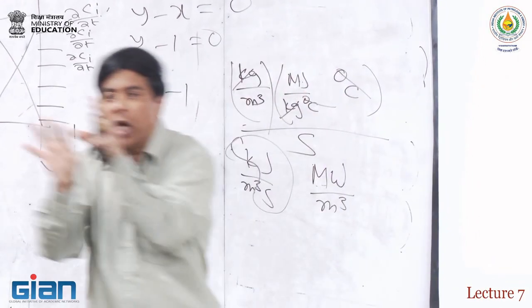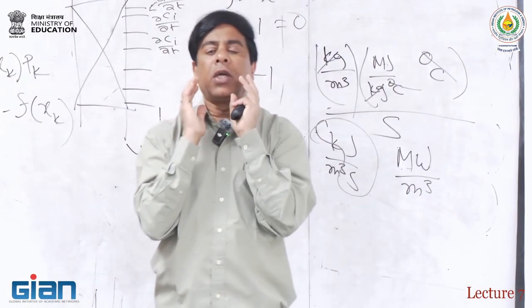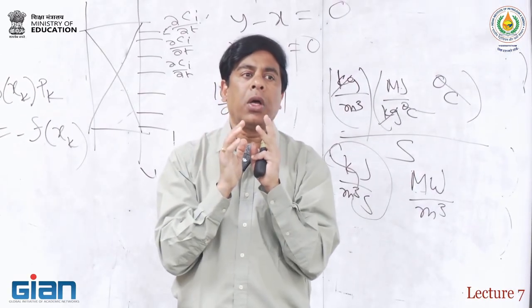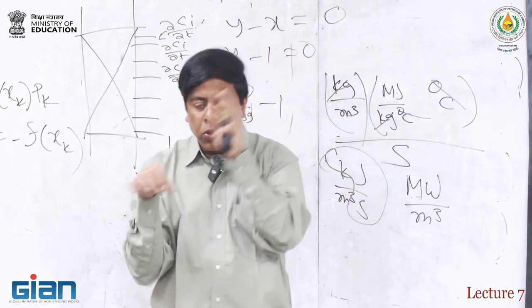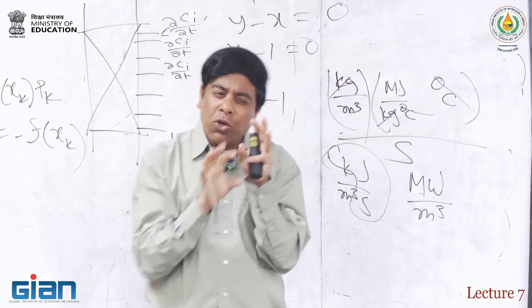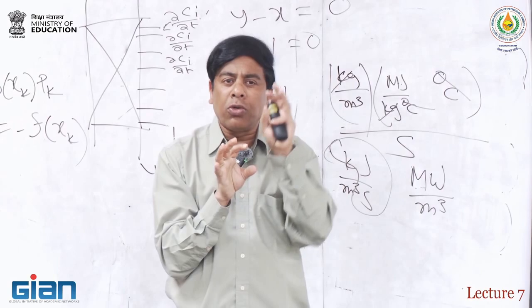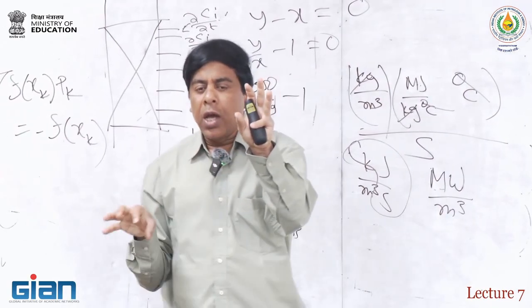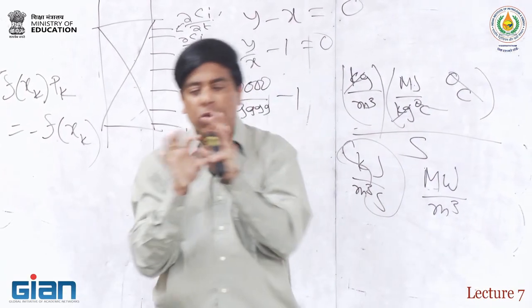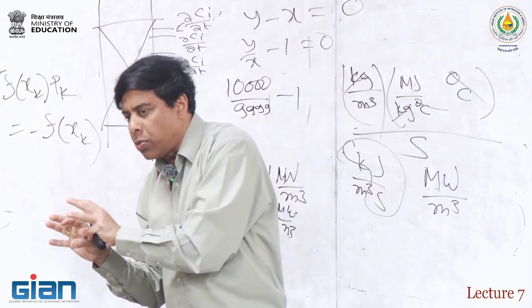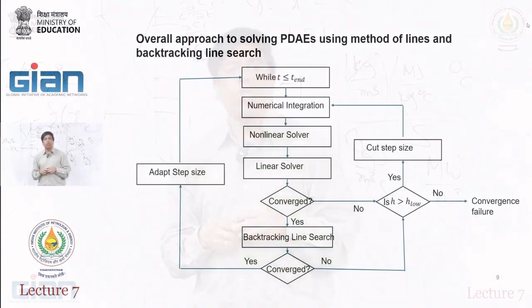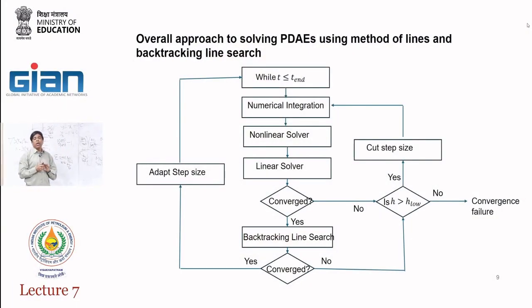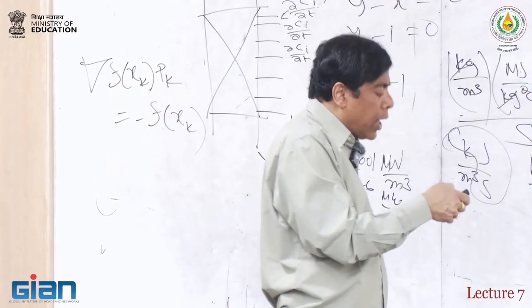Can I make it chunks? That's the power of the linear equation solver behind the scene, because it is doing all of those things to see, do I need to solve this 10,000 by 10,000, or can I separate it into 1,000 by 1,000, this 1,000, this 2,000 by 2,000, and then combine those things. That's what the linear equation solver does. That is the guy that takes a lot of time.